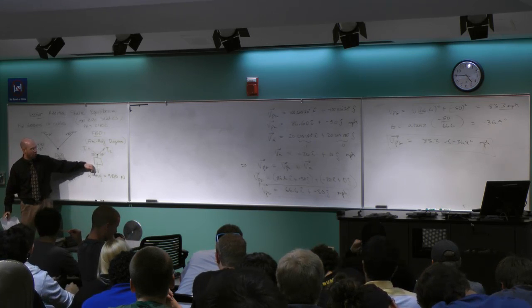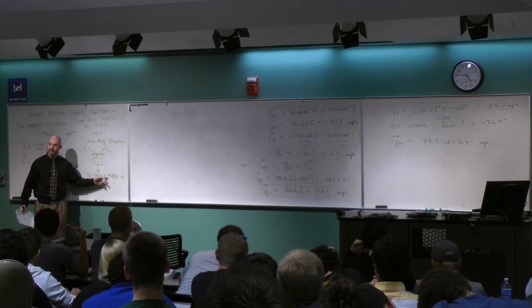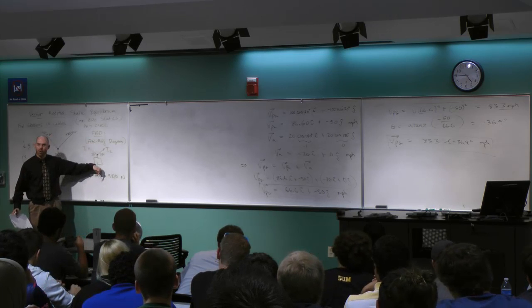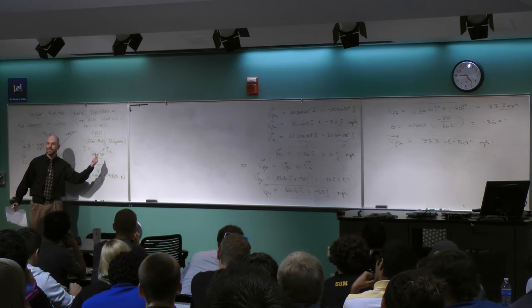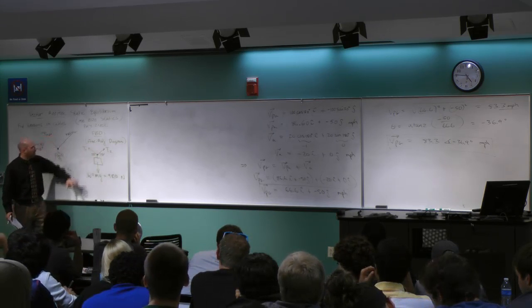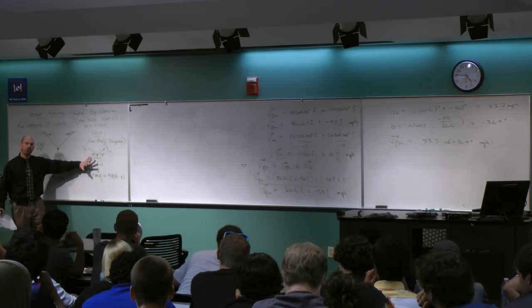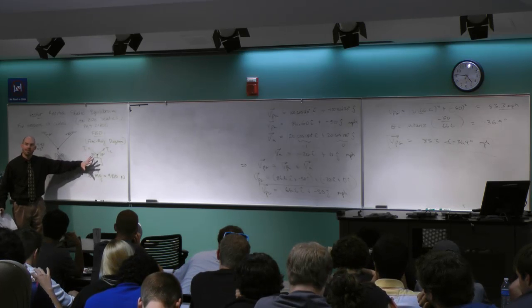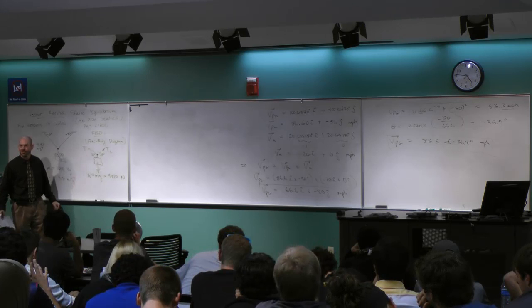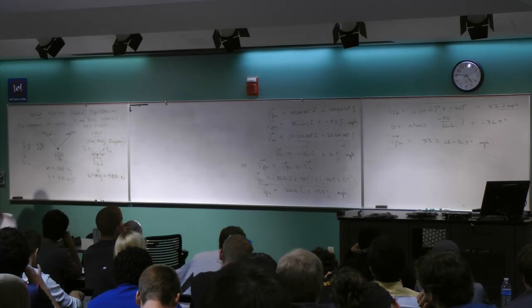If I draw the arrow down and then I also label it negative, some people would interpret that as a negative force this way is actually a positive force that way. And you start to get confused with double negatives and such. So general rule of thumb, on a free body diagram, if you know the direction of a force, draw it that way and don't add an additional sign on it. That way you don't get confused. Is that clear?